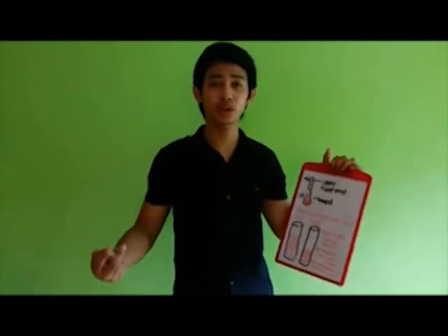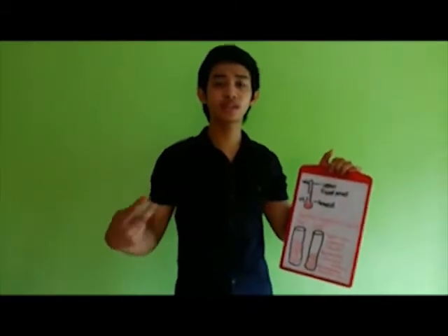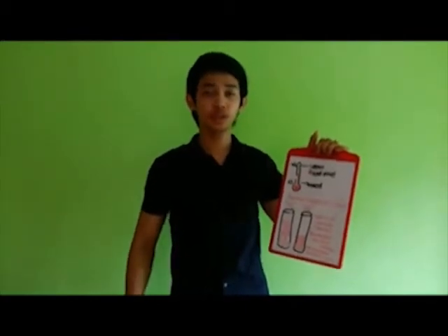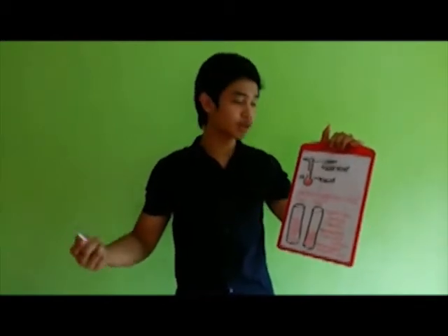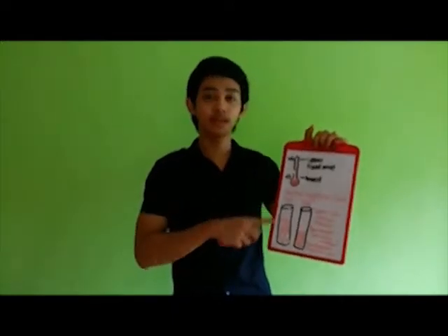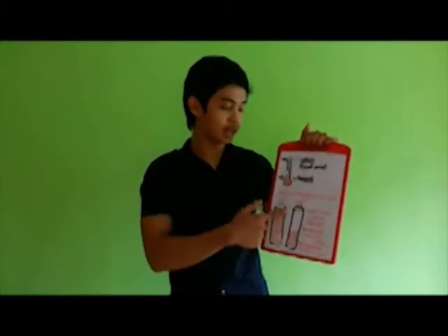The one that I am going to discuss is the liquid in glass thermometer, which is an old type. And we know that there are new types, but the principle behind is basically the same. The principle that is used for this is thermal expansion. So obviously, if the temperature is warm, the molecules in the liquid tend to move fast, making the liquid rise. But when the temperature is cold, the molecules in the liquid tend to move slow, making the liquid go down.